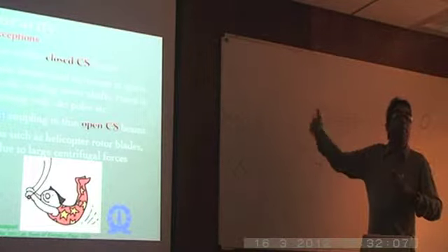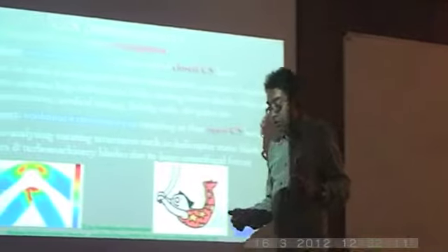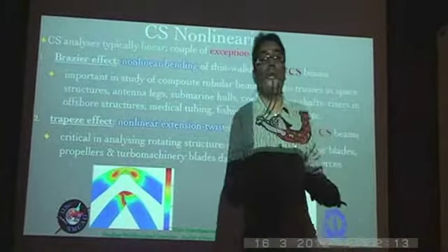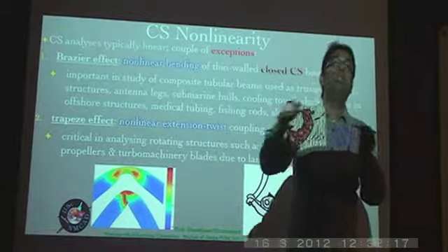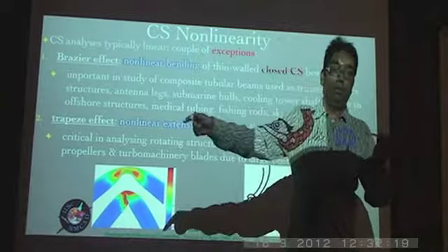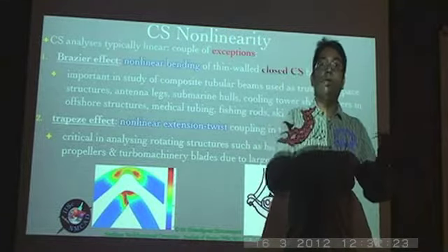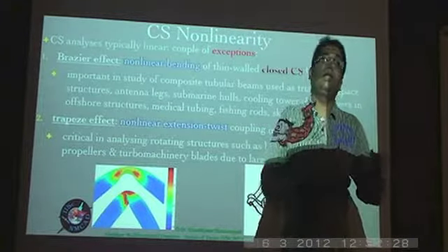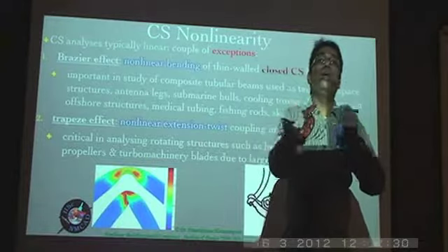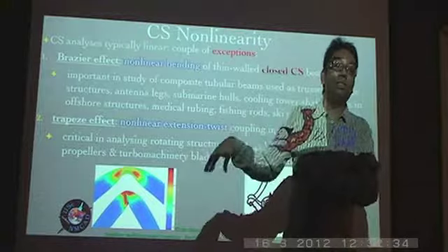There will be many such things. And again, there is also a way of handling that, because remember that we have freedom over the choice of the reference curve. So you can choose the reference curve according to the convenience. Depending upon where you choose the reference curve, either as the loci of the shear centers or as the loci of the centroid, you might be shifting this particular effect to different regions of the analysis.